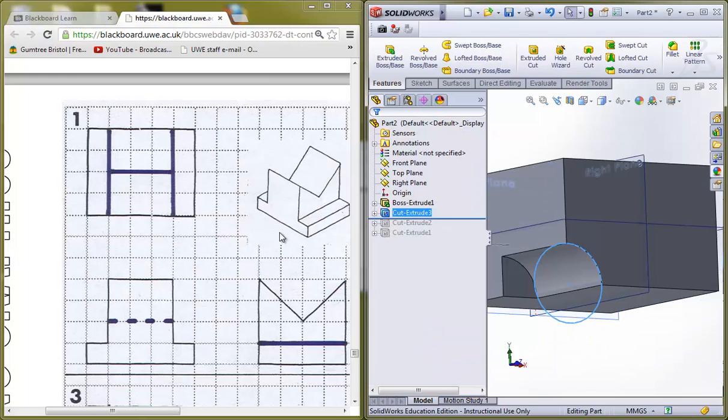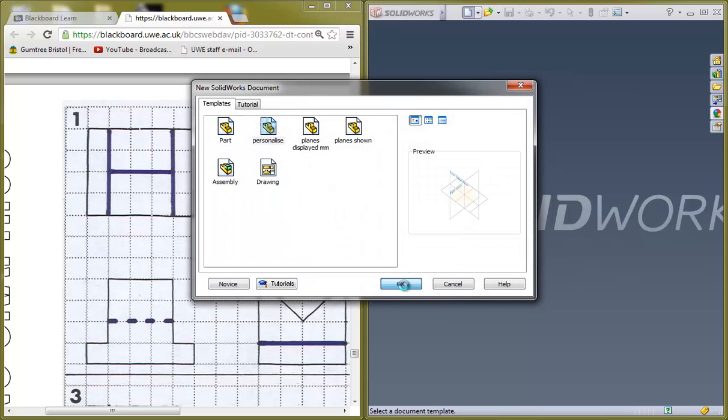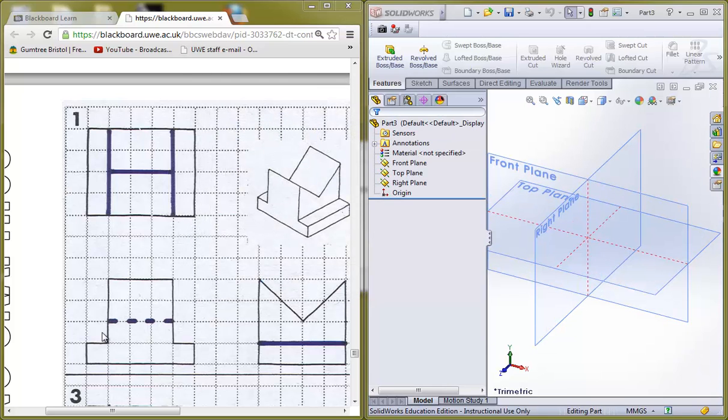So in this example, we have a couple of ways to go. We can produce this sketch, extrude that out at this distance, and looking at it sideways, we can extrude cut that V shape out. Or again, we can produce a big box. We can chisel out this rectangular section, and looking at it sideways, we can delete this triangular shape here. So let's start with